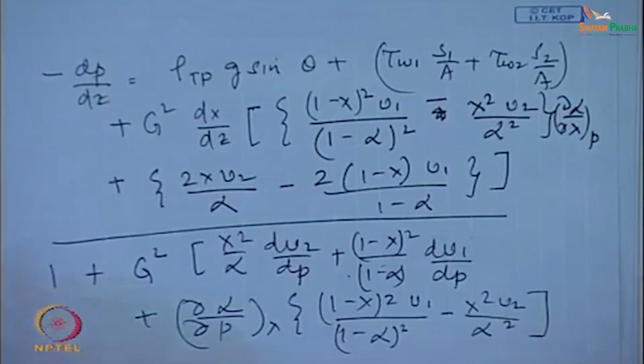So, just keep in mind when you are given a derivation in your exam, this is just a generalized form I have written. Depending upon the problem in question you will be eliminating the basic terms from the very beginning, so that your expression or your derivation becomes simpler. So, we had just assumed these two things: that alpha varies with quality as well as pressure, very justified, and that both the specific volumes or the densities are functions of pressure.